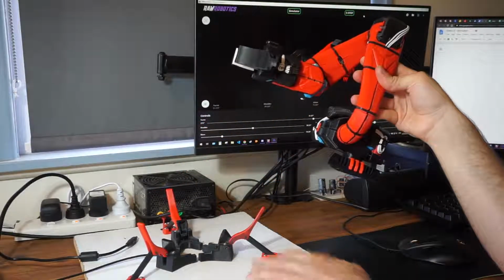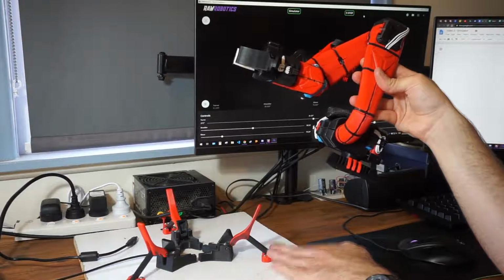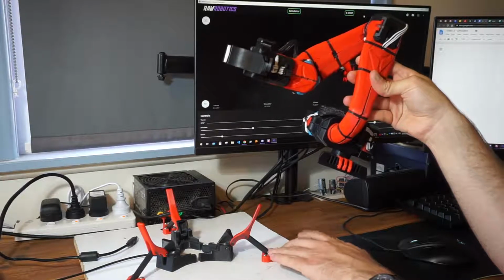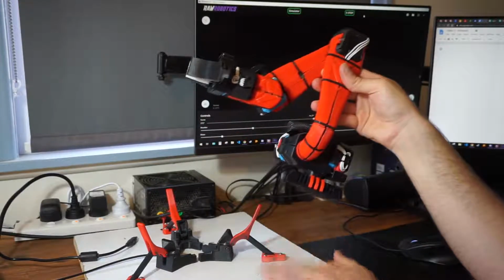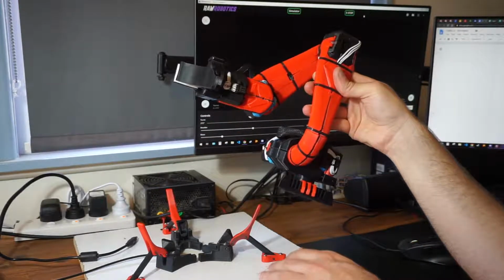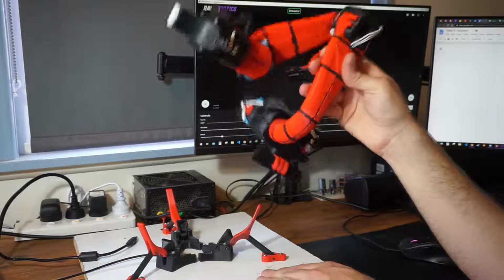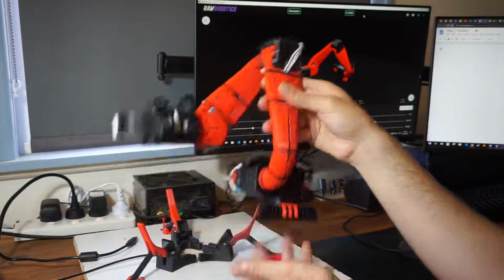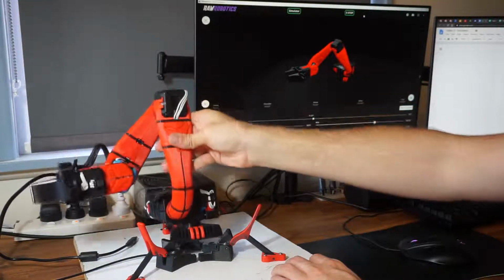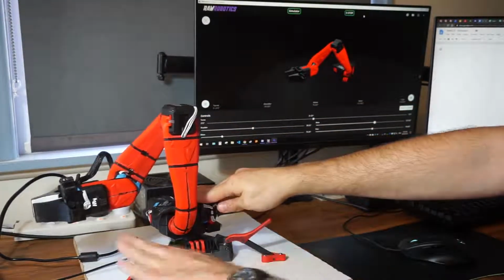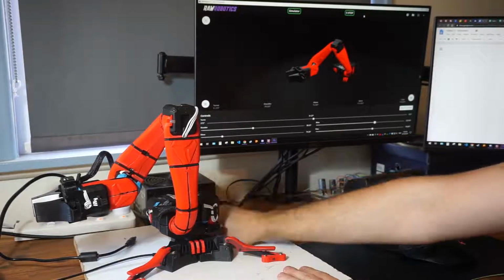So your robot may have come with one of these quick mount bases. This is an old version. We have a nice new version now, which is a bit lower profile. This makes it easy to mount the robot to the desk without having to screw and unscrew the robot each time you want to use it. So simply line up the 3 points, push down a bit, and then do the final latching of those 3 clips.